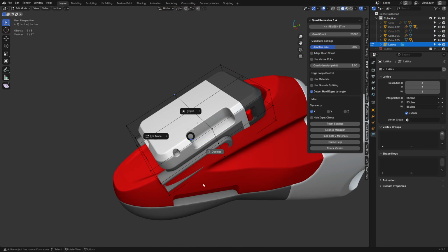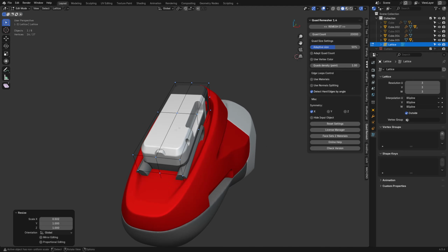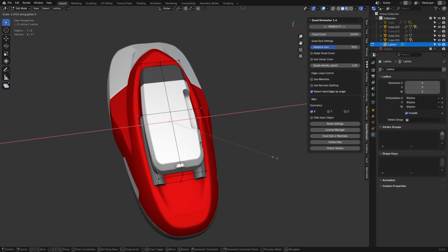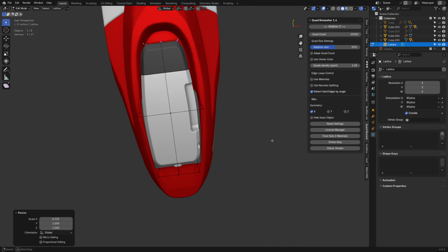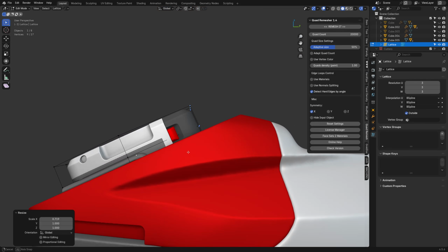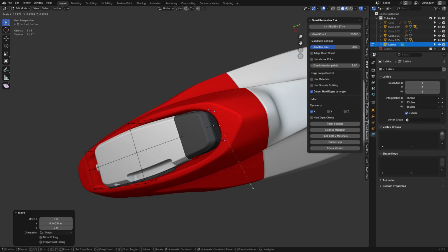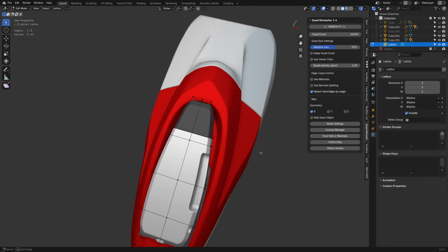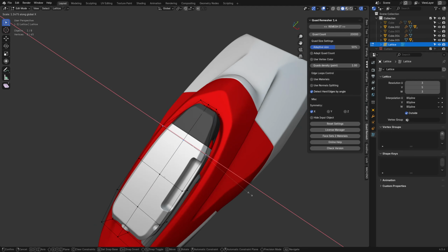But we should be able to get in here and squish all of it now with the lattice. But we Alt-Z, grab the middle. We can deform it. Maybe we take this one and scale it. Move it back. Scale it down more. Okay, so our lattice, we could probably increase twice here. So we can change the curve.